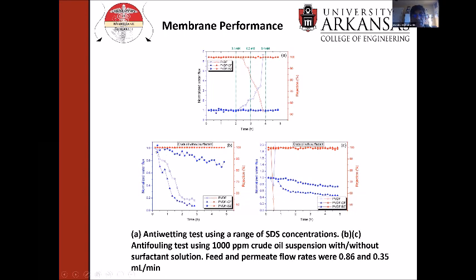And importantly, the rejection of sodium chloride for all membranes remains approximately constant and very high. So adsorption of oil will not lead to breakthrough of water, but it will lead to fouling and decrease in flux. So finally, we put both together. We put SDS and the mineral oil together in the feed stream containing 3.5 weight% sodium chloride. So what you see here, again, is normalized flux in figure C on the left-hand side y-axis versus time on the x-axis, and the right-hand side y-axis is rejection.